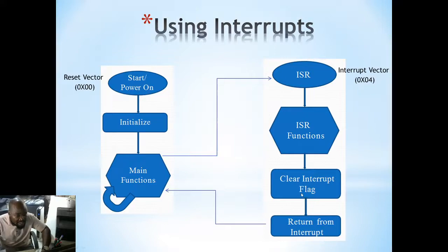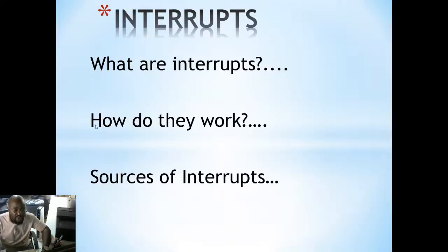So after servicing the interrupt, you need to clear the flag so that when you return, you wait for another interrupt. You are not automatically taken back because you didn't clear the flag. It's very important that you clear the interrupt flag, right? So that's basically how we make use of interrupts in our PIC microcontroller.